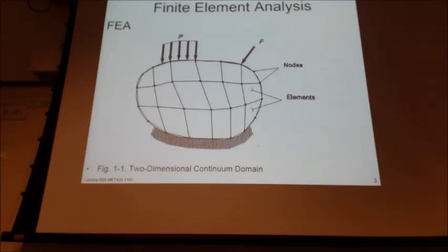The mesh is what we describe as the group of elements that are canvassing the geometry, and the solver doesn't understand the geometry. The solver understands the nodes and elements, and that's what it's working with. So our mesh, our nodes and elements, have to approximate our geometry well to be able to obtain a good solution.